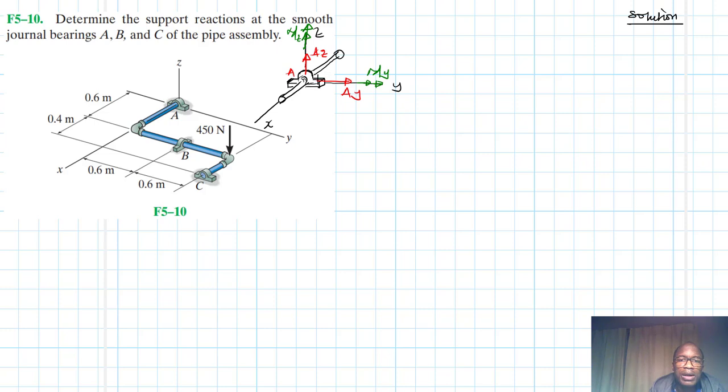This is where you just have a member that is not supported elsewhere. But the moment this particular structure is supported elsewhere, you can neglect these moments. You don't need them. They're as good as not there, because you're just going to have unnecessary work. You can neglect these moments if this structure is supported elsewhere, because they'll still be equal to 0. I wanted to talk about this because I received a question regarding these